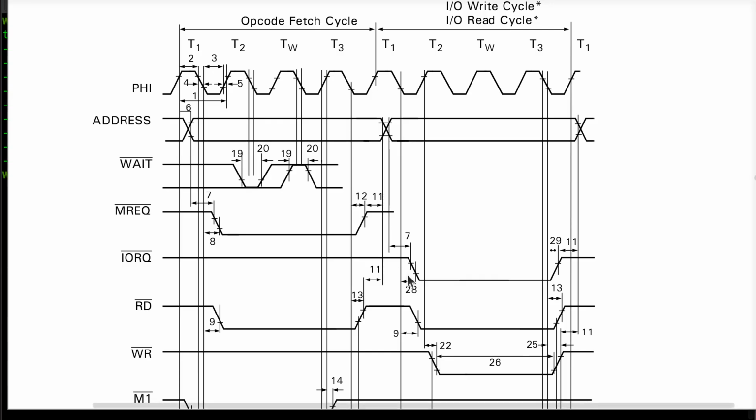So to recap here, I want to read from the FPGA. The FPGA needs to latch its output data, or at least acknowledge that a read has taken place, on this falling edge at the end of T2. And when there's a write operation, the FPGA should consume the data from the CPU on the falling edge of TW. And it should do it once and only once in each situation, so that if an I/O peripheral does something like advancing a counter every time data is written into the device, it works.